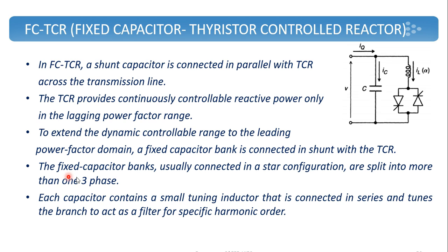So the fixed capacitor bank is usually connected in star combination. It will be connected to the three-phase supply. So even though it is shown as a single phase circuit, there will be three capacitors for the three-phase supply. The capacitance will usually be connected in star configuration.